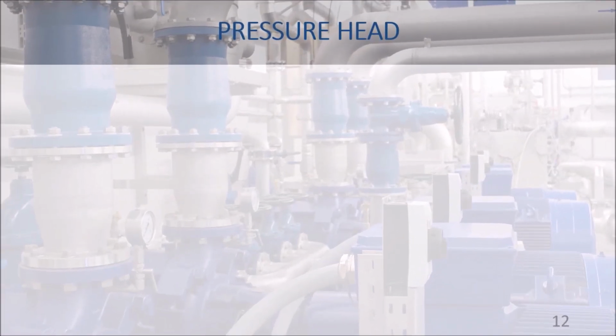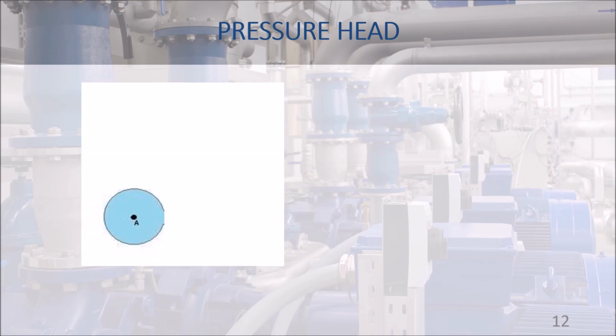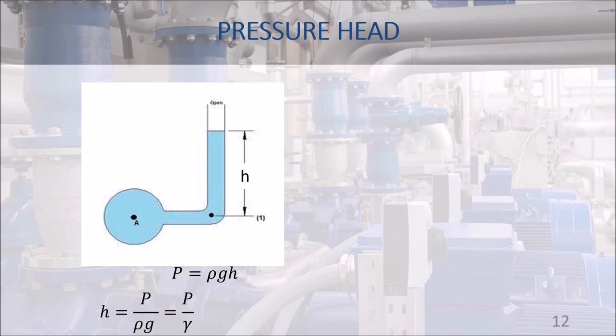A very well-known term in hydraulics is the pressure head. Assume a pipe you want to measure the pressure inside. Drill a hole and connect to a vertical piezometer tube which will read a height h. The pressure is equal to rho g h. This equation can be expressed in a different way as h is equal to P over rho g, or P over specific weight gamma. H defines the pressure head. So the head is another unit of pressure, like the bar and psi.